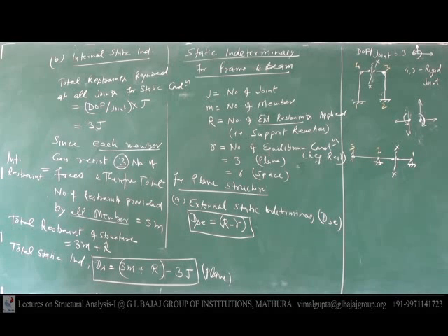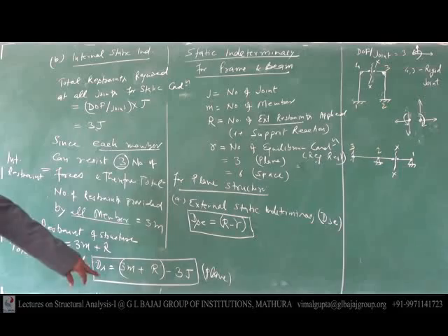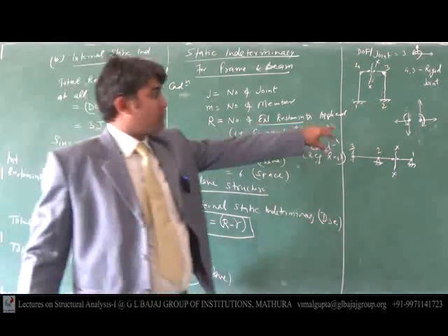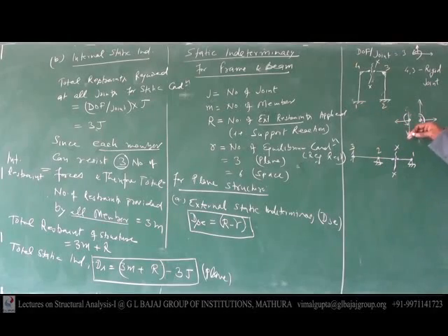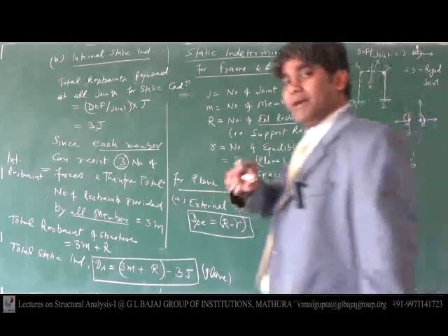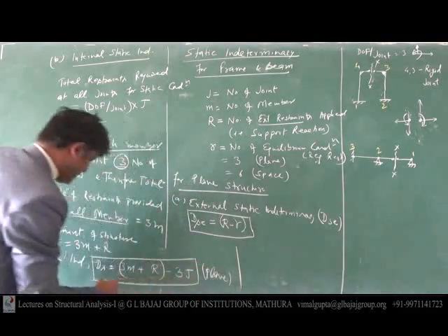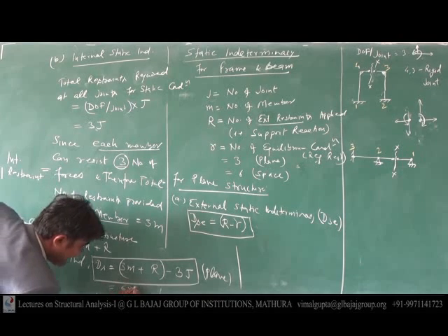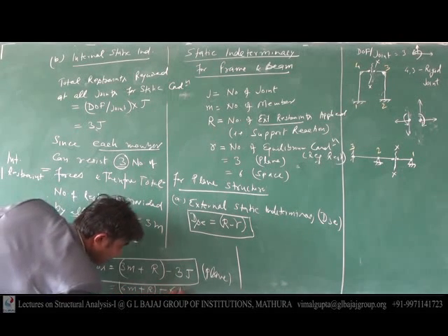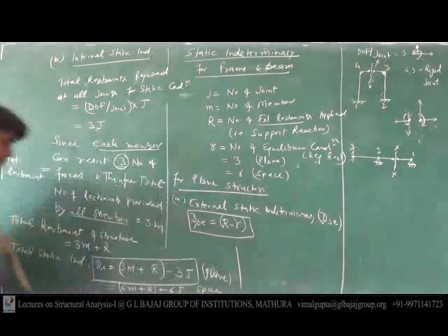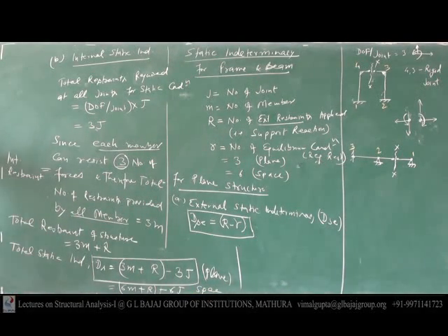6m plus r. Yes, sir. Why 6m? Because every member can have 6 number of forces. That's why for space, write here: Ds for space it will be 6m plus r minus 6j. It is for space. Clear to everybody? That should be very much clear to all of you. Remember, but with understanding.